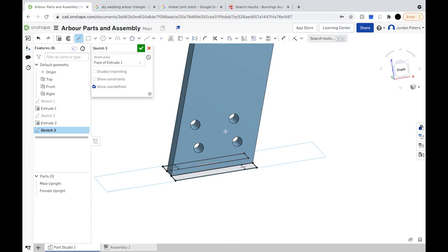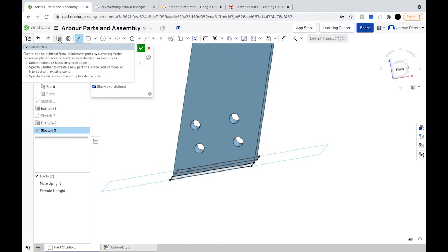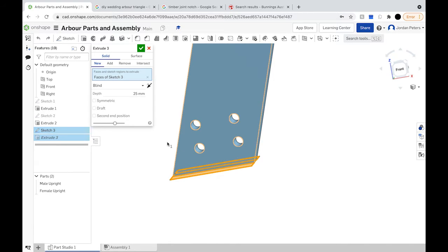Now we know we have to extrude at least 30, 60, and then half of 12.5, which will be 6.25, so 66.25 upright. We know we have to extrude at least that high. So if it's 66, we might go to maybe 80. And we can work on that extrusion. We'll have a look at what looks right. But we'll go through and extrude both of those.